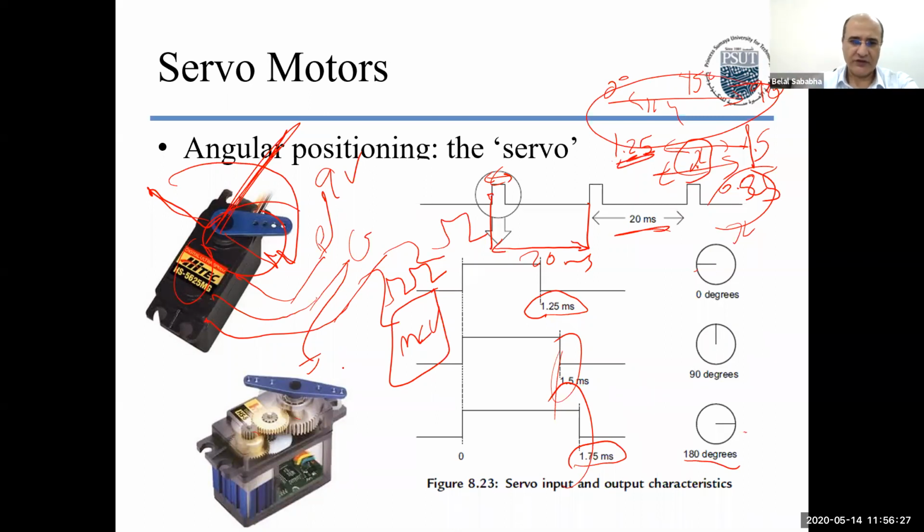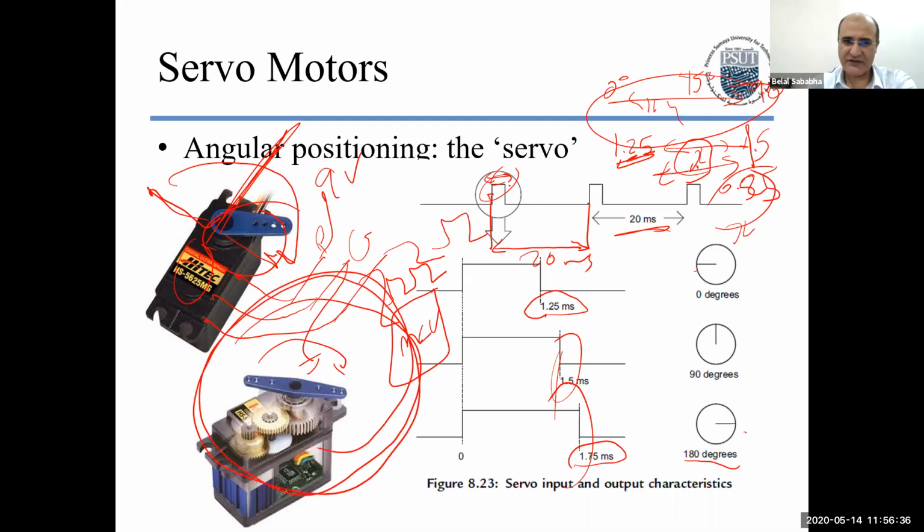And you can control the speed. Now this range also, for the 360 ones that move 360 continuous, in this case, the angular position is decided by the pulse width, okay? But for the 360 ones, the pulse width decides the speed of rotation. It has a maximum speed, minimum speed, and you start changing the pulse width to change the speed.